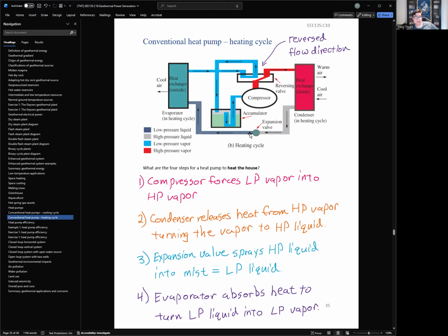So you have to remember, when it comes out of the expansion valve, this temperature is like 0 degrees Fahrenheit, freezing cold. You get 0 degrees Fahrenheit coming to the evaporator core outside your house. Now, outside your house, it's cold, but it's not 0 degrees Fahrenheit cold, right? If my liquid is 0 degrees Fahrenheit, but my outside temperature is 50 degrees Fahrenheit, that's a big difference. To us, cold is cold, but to the heat exchanger, I could take 0 degrees Fahrenheit and 50 degrees Fahrenheit, and I could pull 0 degrees up to maybe like 30 or 40, right?